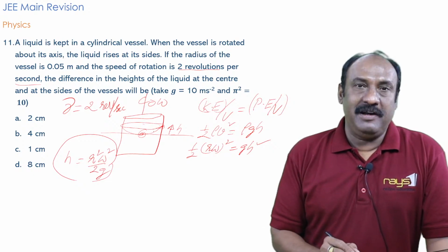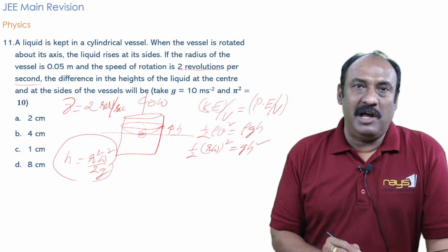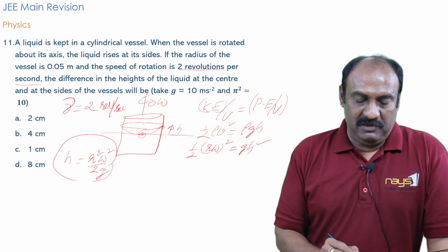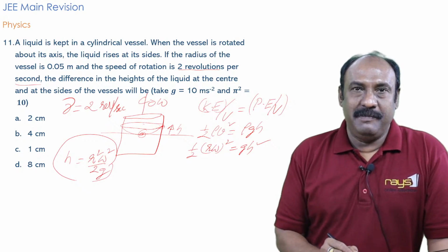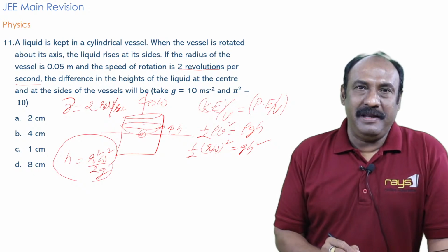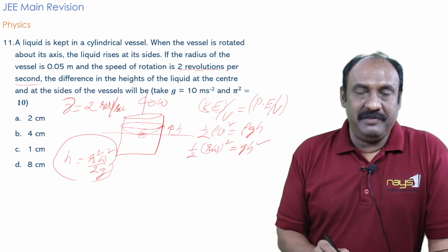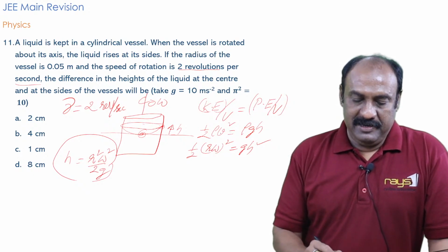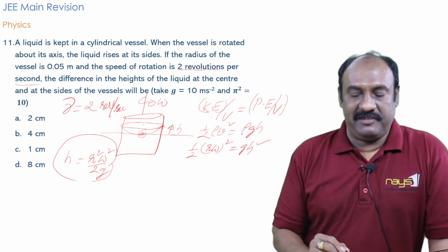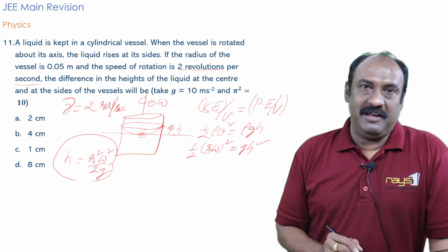For this liquid, all of you know the total energy remains the same. With respect to this level, the potential energy per unit volume is 0. At this point there will be some potential energy per unit volume, but the kinetic energy is almost minimum. So the maximum value of the velocity or speed of the rotating liquid is written as r omega, because it is under perfect rotation with constant angular velocity omega. Due to that, v is replaced by r omega, rho gets cancelled. From this, h is given as r square omega square by 2g, the final equation.